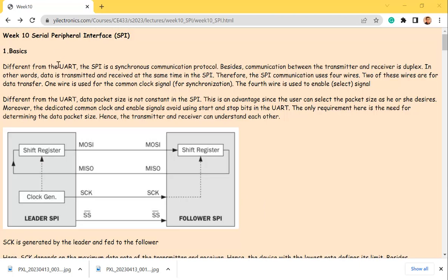Okay, so the plan for today is first I'm going to give you the SPI modules of the light sensor. These are pretty simple, just sensing the light intensity, and it has an SPI communication port. So you can directly plug into your FPGA, and it is able to send all the digital signals through SPI to your FPGA. Very convenient. Are there any other digital modules you can think of that use SPI ports?